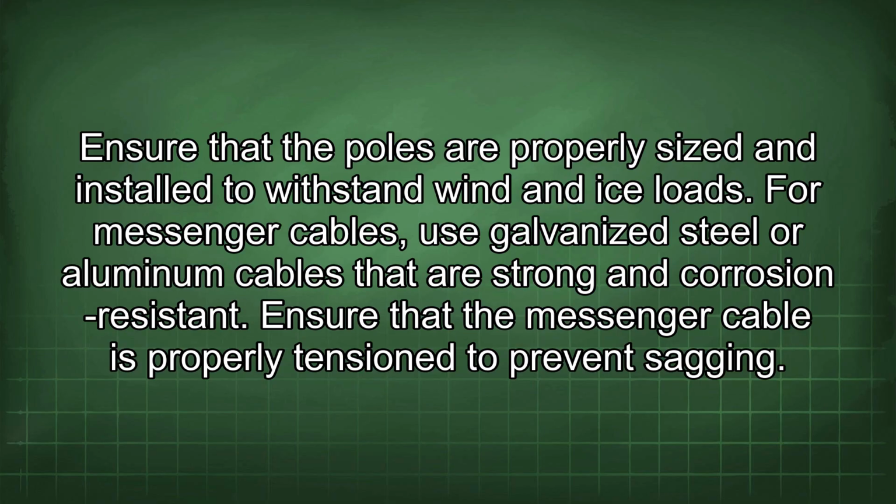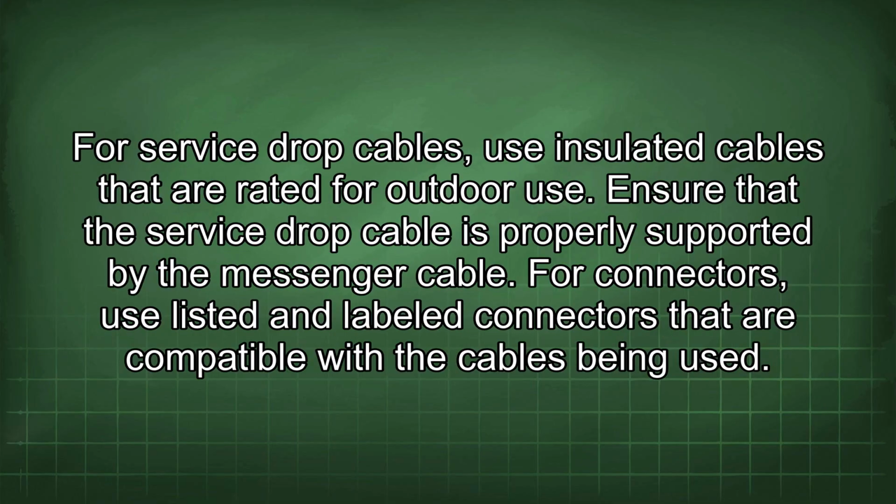For messenger cables, use galvanized steel or aluminum cables that are strong and corrosion resistant. Ensure that the messenger cable is properly tensioned to prevent sagging. For service drop cables, use insulated cables that are rated for outdoor use. Ensure that the service drop cable is properly supported by the messenger cable.